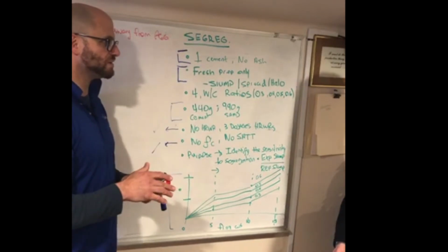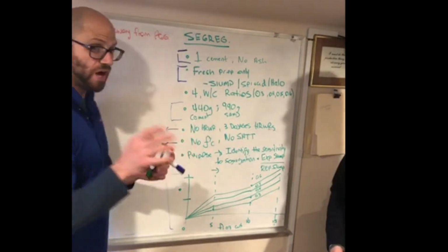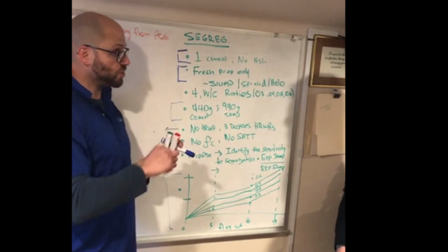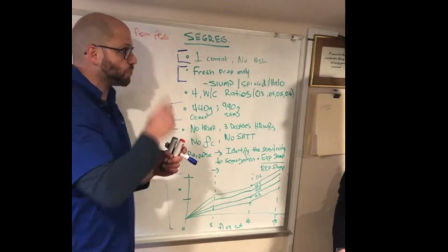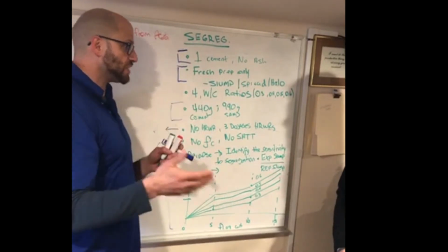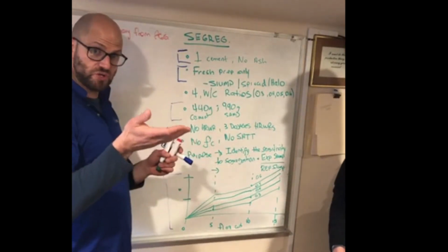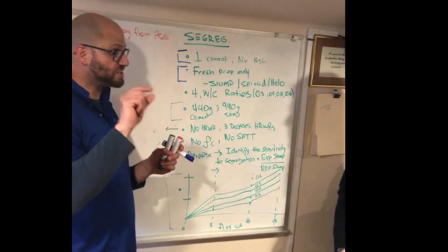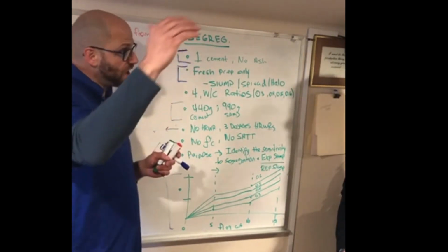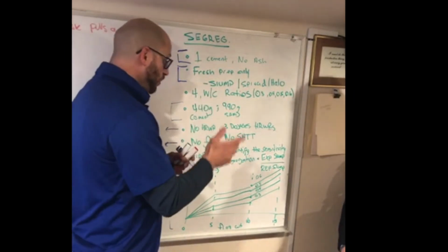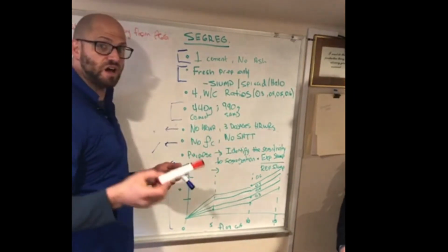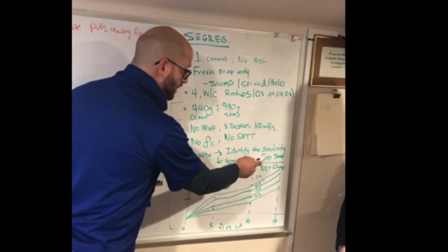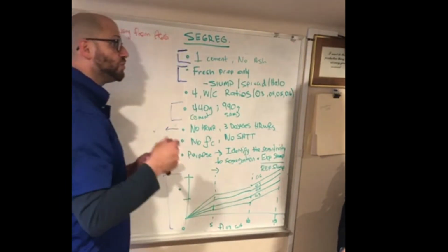Now we talked about this, and what I had said is that as we add more water and increase our high-range water reducer, we're going to see a higher sensitivity to segregation. And as our water cementitious ratio goes up, we should see that sensitivity to segregation either have a higher or lower value. Now, the question should be, what is the definition of sensitivity to segregation? And it's that experimental slump versus the reference slump.